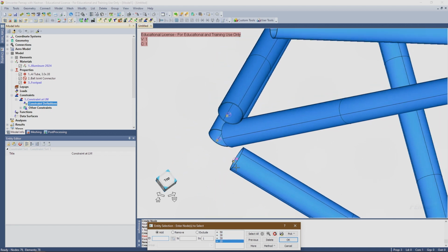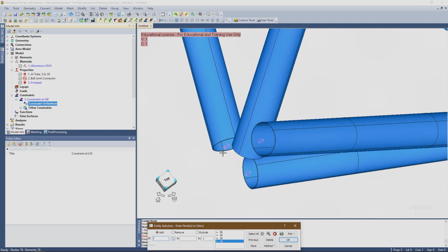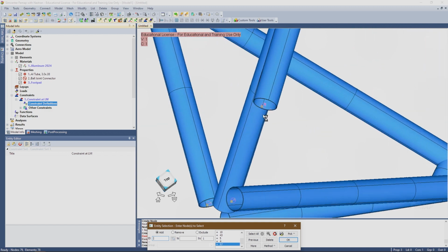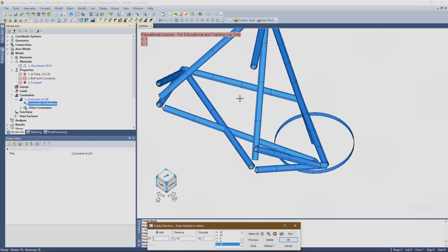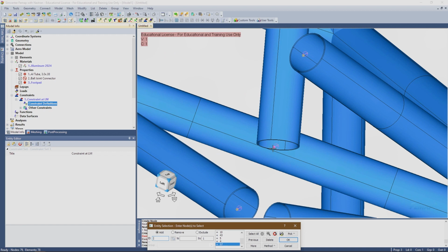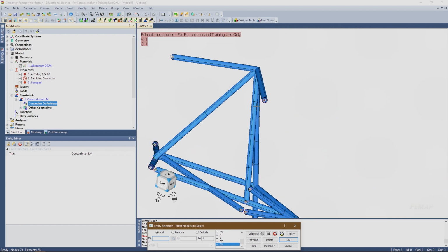So actually, while I'm doing this, I got sidetracked and didn't tell you the other benefit of the spring element. For all this type of stuff, they are extremely easy to output the forces in all 6 directions. So you can very easily analyze the forces on all your bolts with spring elements.